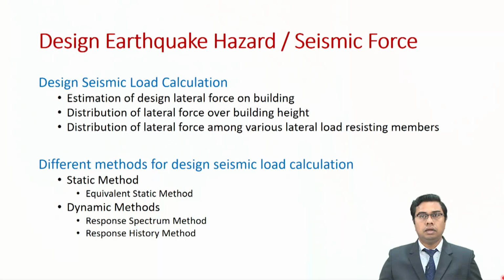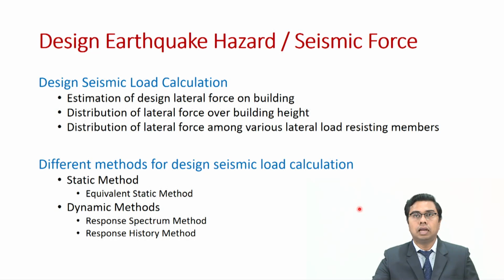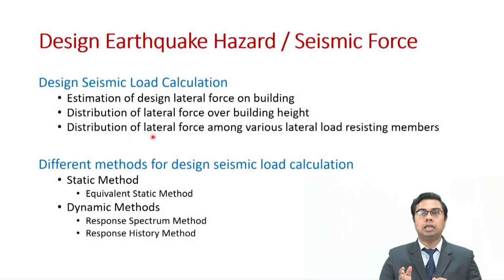With this understanding of dynamics of single degree of freedom systems, we will move to design seismic hazard estimation. In this class, we will look into design earthquake hazard estimation or the design seismic force calculation. In the design seismic load calculation, the first step would be to estimate the design lateral force on any given building. We will distribute the design lateral force over the building height, and later we will also distribute these floor forces among various lateral load resisting members on the same floor.